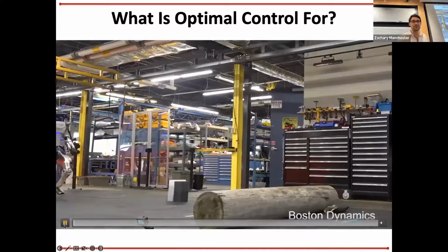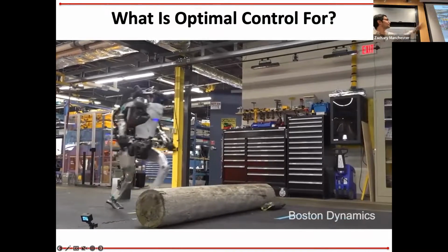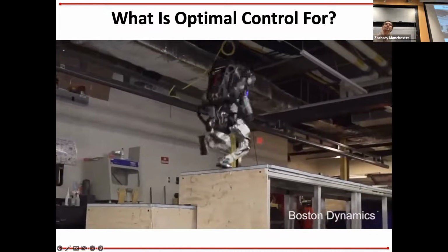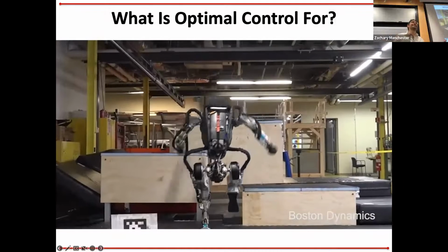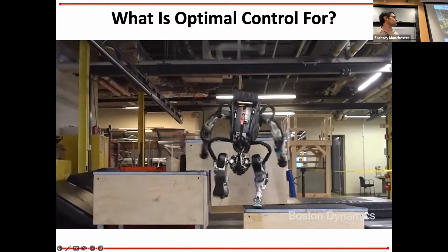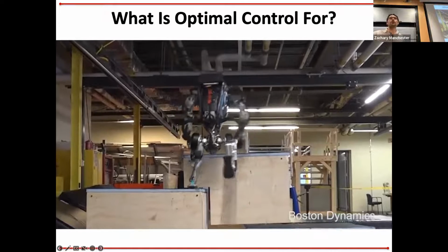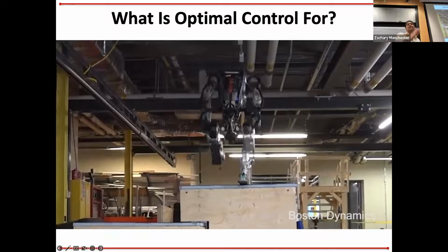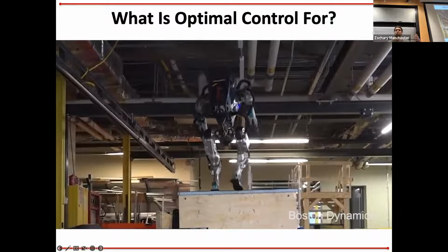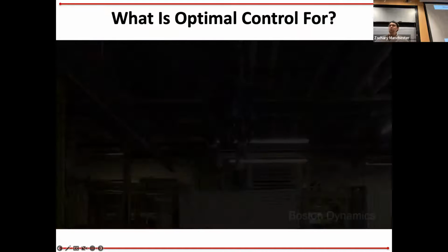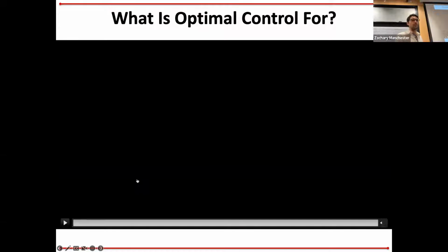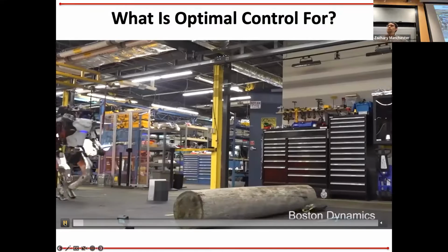Also, super famous, awesome stuff that you have probably also seen, right? Boston Dynamics' Atlas doing parkour moves and dancing videos, all this kind of stuff. Once again, this is MPC. In particular, these guys are doing some really state-of-the-art nonlinear MPC where they're solving basically a whole body. Unlike the dog robot where you can assume the legs are massless, here the legs are super beefy and have a lot of inertia, and you can't model those as massless anymore, right? And you have to reason about how the movements of the legs will couple into the body.